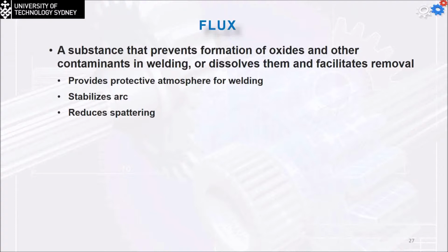Once again, the flux is a substance that prevents the formation of oxides and other contaminants in the welding process, or dissolves them and facilitates their removal. This will provide a protective atmosphere for the welding, stabilize the arc, and reduce the spattering of sparks.